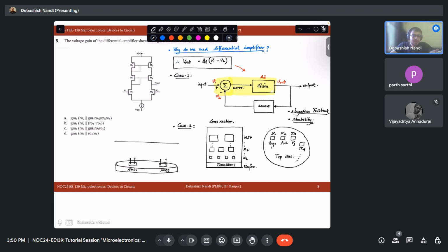Okay. You can use PMOS also in the same substrate by the twin tub technology that you have read in this course. Okay. So let's say this is your ground line. You want to connect your sources to that. Let's say your source is connected here. Your source is connected here. But you want to have two different power supplies for both the transistors. Let's say one you want to operate at VDS equal to 1 volt. Another one you want to operate at VDS equal to 3 volt. Okay. So what will you have?